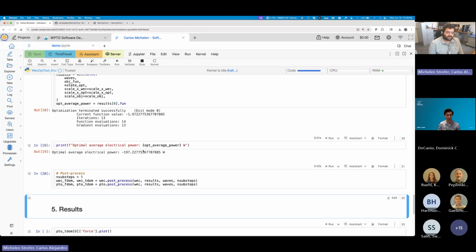We don't look at the time values directly. We look at the Fourier coefficients, but basically each Fourier coefficient is completely arbitrary, and the optimizer can set it to wherever it wants to. There's no structure to follow. But in the case of the linear problem with no constraints, the optimal result will be the complex conjugate. But it won't use that knowledge. Especially later when we add constraints, the problem will no longer be linear, so you couldn't use the complex conjugate there. But that's a good question.